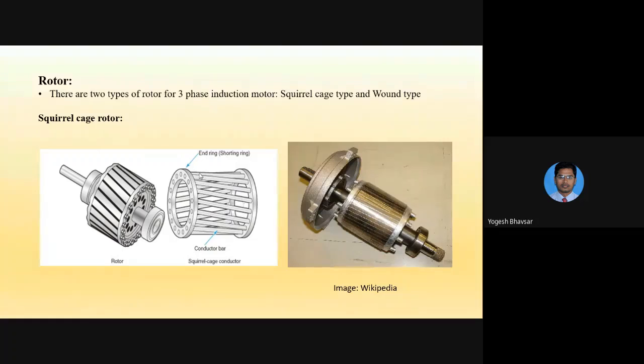In this rotor there will be no winding. Instead of winding, there will be conductor bars. These bars you can see are conductors made from copper or aluminium. The end connections of these conductors are connected to end rings on both sides. Hence, the conductors are permanently short circuited, so that the current will circulate through these conductors. So this is the complete assembly for the squirrel cage rotor.